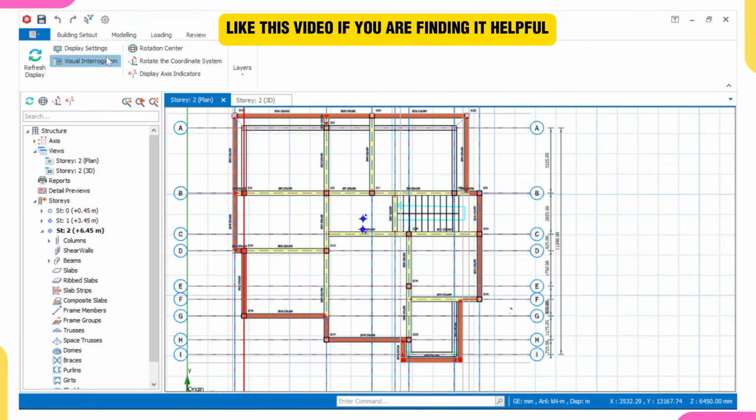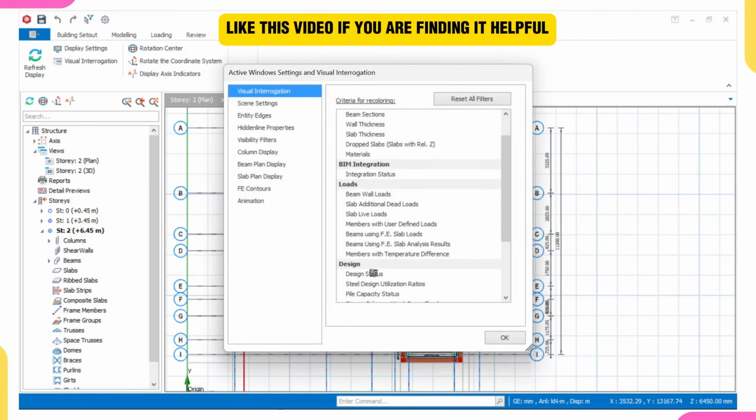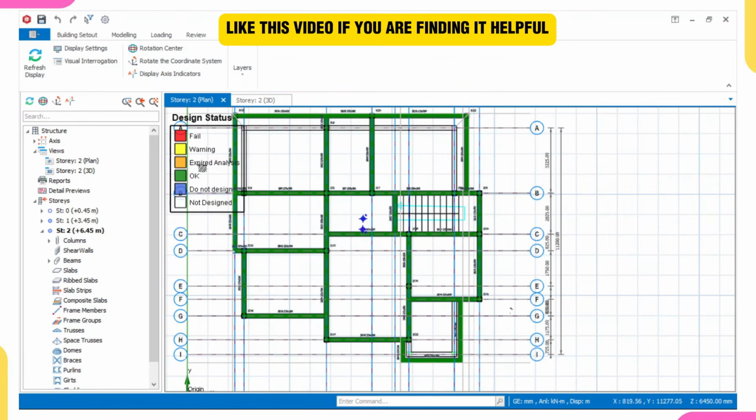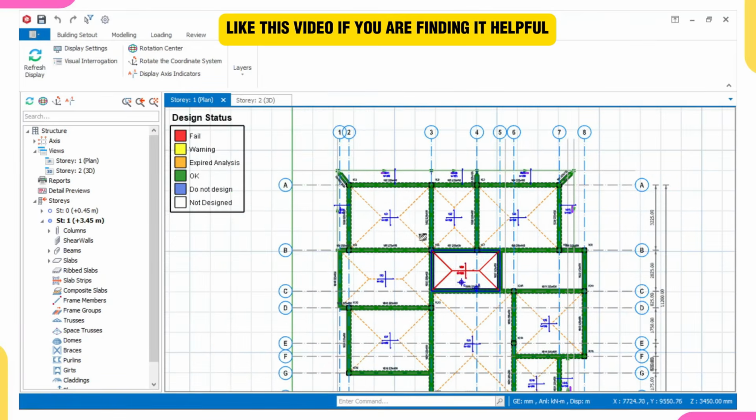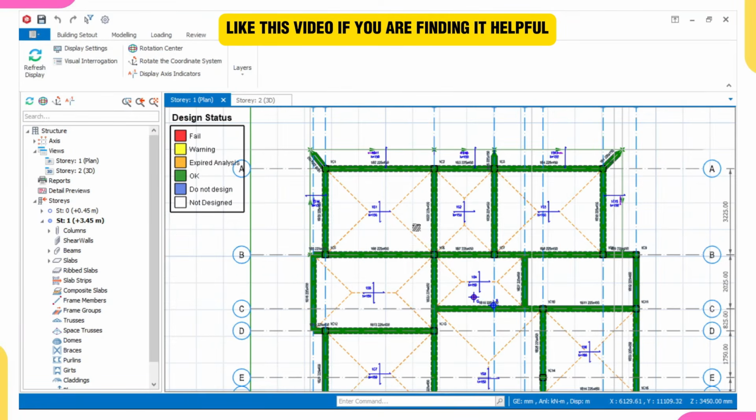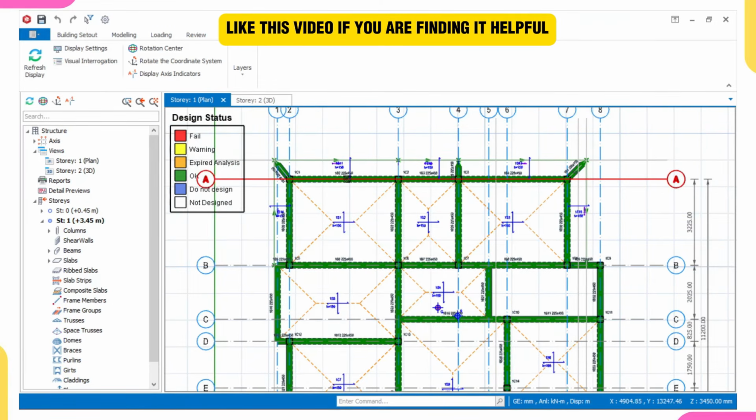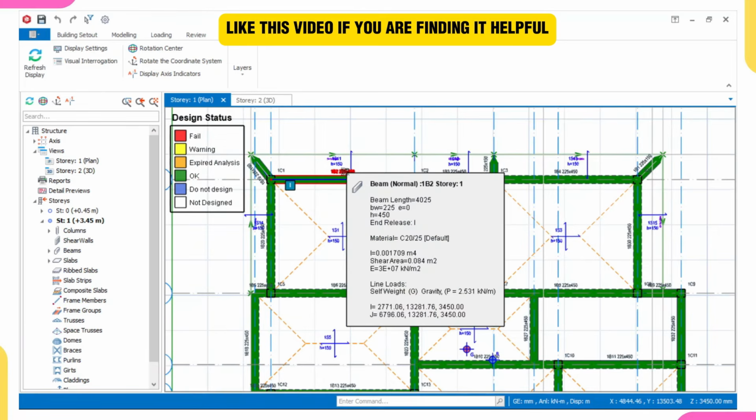Okay, we'll turn on the design status again. So click on design status, we click on OK. So let's go to story one. We'll double click. So we are now in story one. Remember, even if it passed, even if all of them should pass, do your interactive design. You must carry it out because sometimes the software might over reinforce. So if it's over reinforced, you know how to go about it.